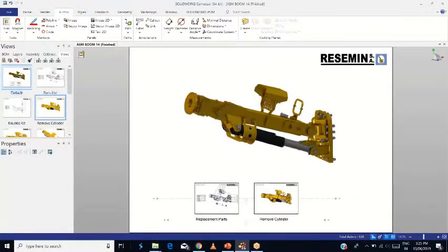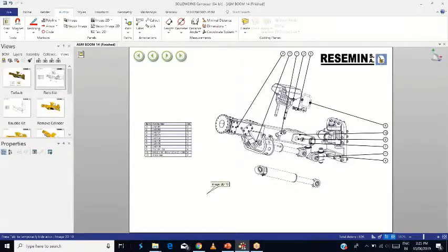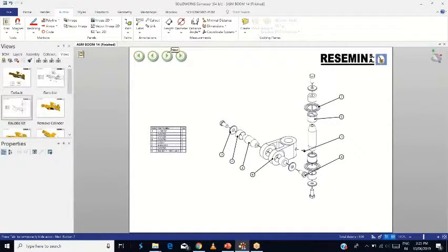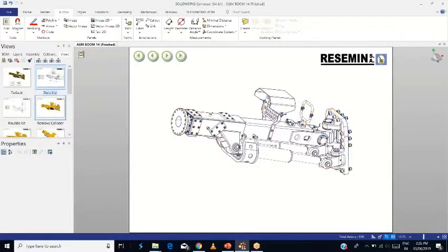Okay, and again, let's see how to remove the cylinder process or the replacement part. If someone wants to check the replacement parts in that particular boom or pin in that particular assembly, he can actually see that. In that case, I'll go back, and I'm segregating the assembly into minute details, so that I can see what part I'm really looking at. If I want to replace this C04726, I can see that this is a bill of material item 7 which has two quantity, so the customer who is looking at it can see that this is the place where I want to replace the part, or this is the part which I want to buy. So many options you'll have. And again, you can come back and see back and forth and see how it works as well.